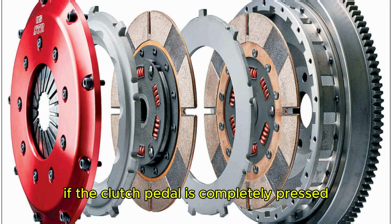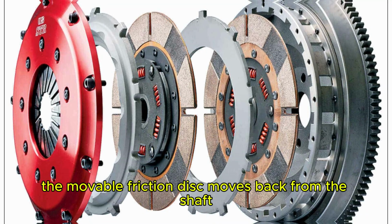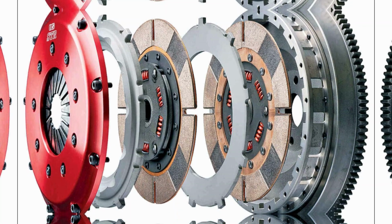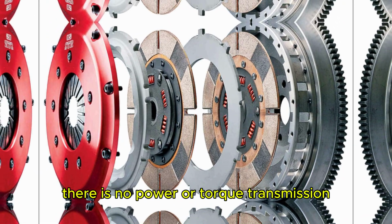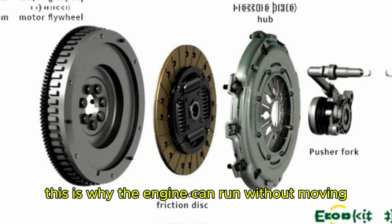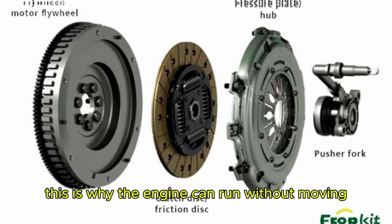If the clutch pedal is completely pressed, the movable friction disc moves back from the shaft, which disengages from the flywheel. There is no power or torque transmission because the pressure plate is not applying any axial load. This is why the engine can run without moving.